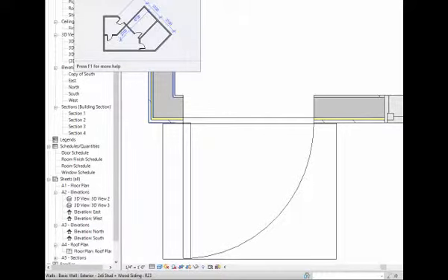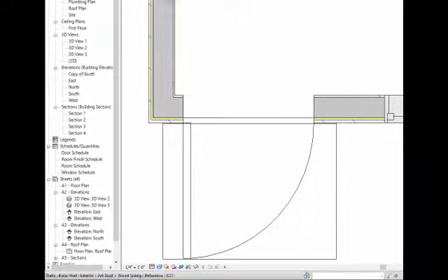And let's talk about what a good dimension drawing looks like. So I'm going to choose the align tool. You have a choice here, even before we start drawing, about what you would prefer the dimensions to stick to. So do you want them to be the wall center lines? Do you typically want to do it to the faces or the exterior surfaces? I always tend to do faces of core. It just makes your life a little bit easier to pre-select this. You can always change it. But I usually go for the faces of the core.